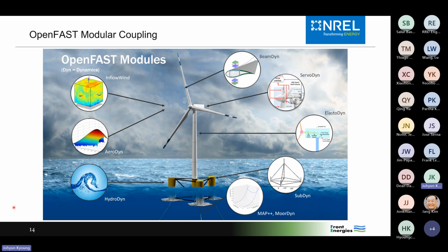Hydrodynamics, our HydroDyn module, soon to have Seastate in there as well. This has a hybrid combination of potential flow. If you have a semi here, you can have either one big potential flow body or separate potential flow bodies for each column of the floater. It's a hybrid of potential flow and strip theory calculations. You can also have the pontoons and braces with an extended Morison formulation. But it's a hybrid, so you can choose whatever combination you want.